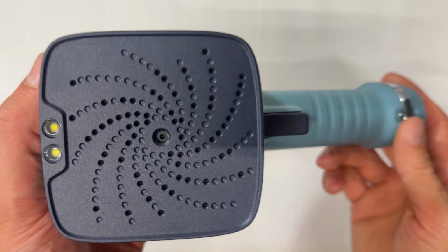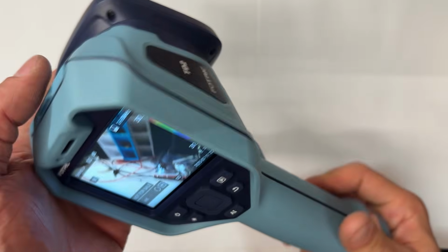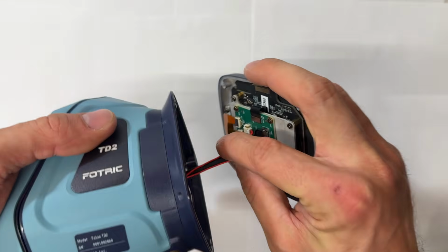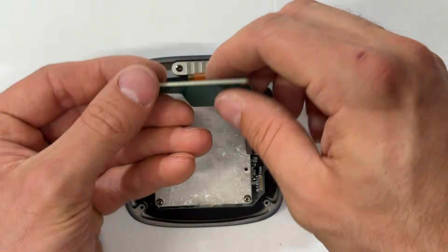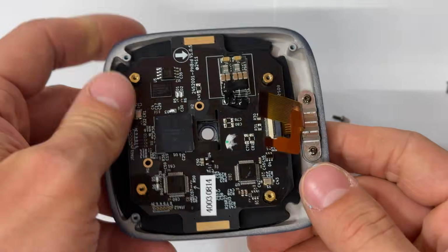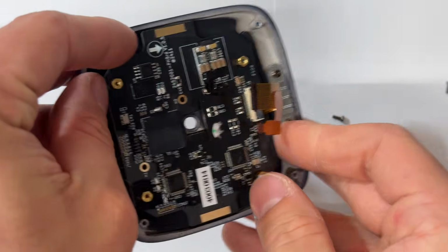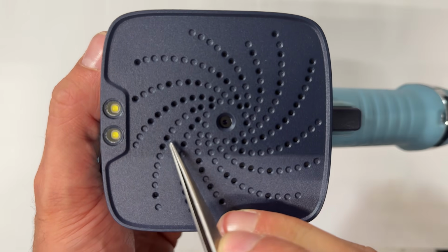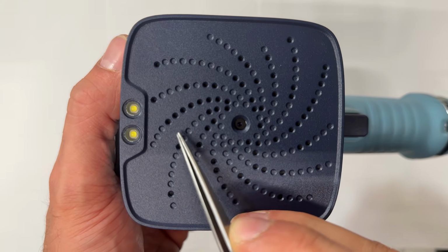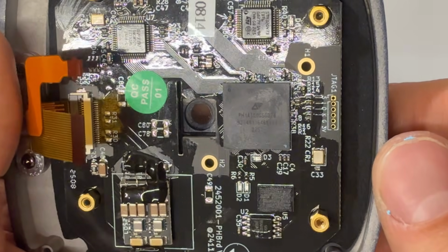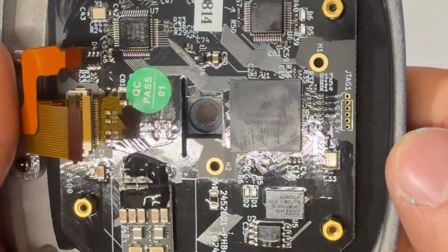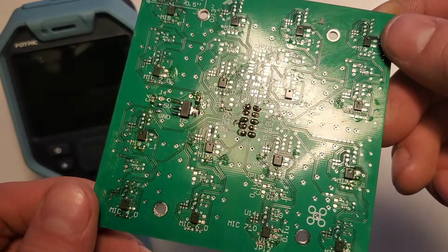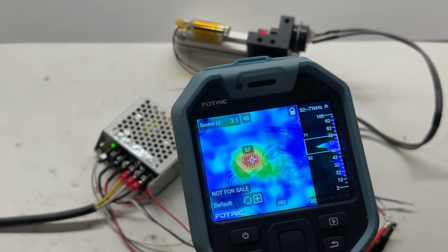An acoustic camera really only consists of 2 parts, at the most basic. There's an array of microphones on the front that pick up the sounds we're looking for, and some kind of data recording or processing that takes information from them and converts that into an image. For this camera, there's 64 microphones, placed in this sort of spiral pattern on the front, and an FPGA and display built in, so it does all the imaging in real time. This brings up a bit of a question. How do we turn the data from a bunch of microphones into an image?